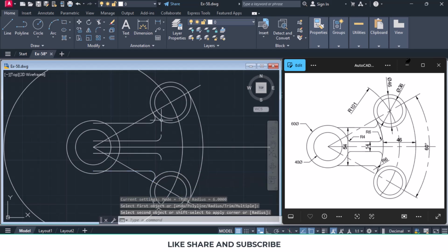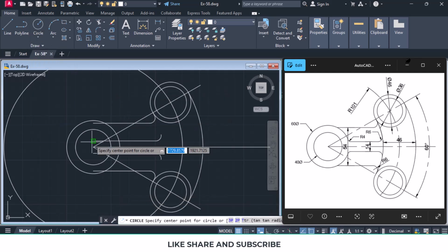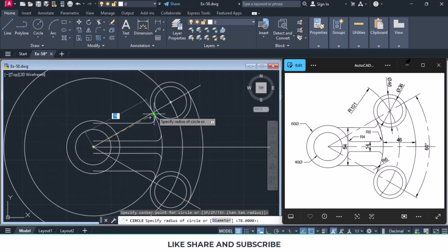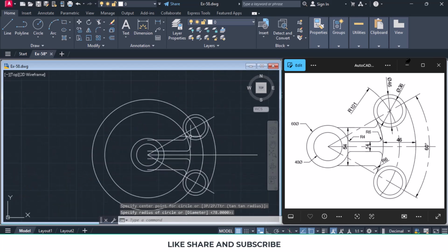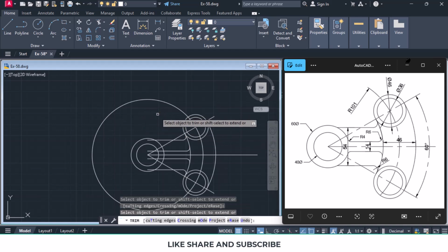So this is also filleted. If your circle is lost, select circle, center radius, click over here and click over here, and then TR for trim, and trim the unwanted part of the circle. So all these fillets 1, 2, 3 and 4 are done.